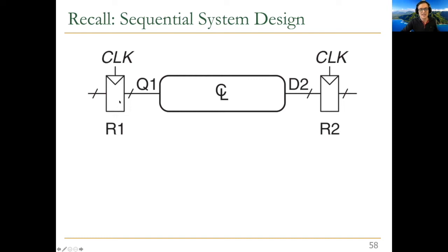You have some system, there are some inputs which are in this register, let's say, or it could be based on flip-flops. And then you operate on those values. You do something combinational that results in some output, and then you latch the data in some other register. And this takes some clock cycle time. And this is really the clock cycle time of your processor, for example. And we will see later on how this is determined in pipelining. Don't worry about that right now. But assume that we have a system that operates based on this.